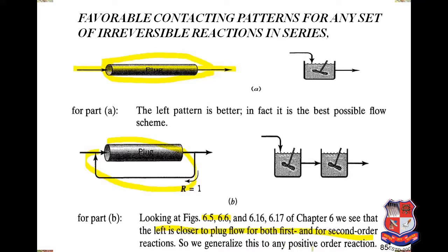So we generalize it to any positive order reactions: a plug flow reactor with a small reaction recycle is definitely a better option compared to two CSTRs in series.